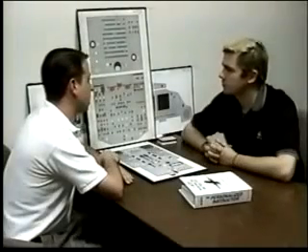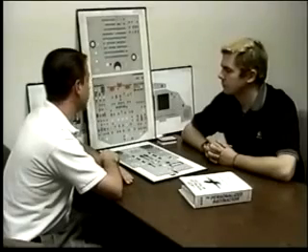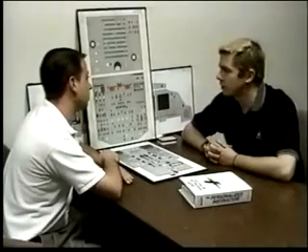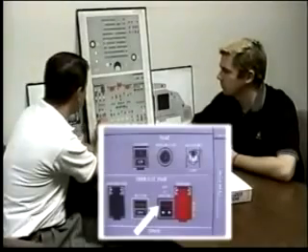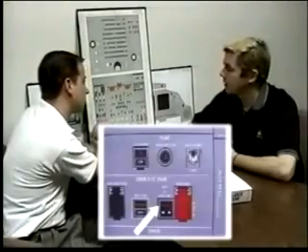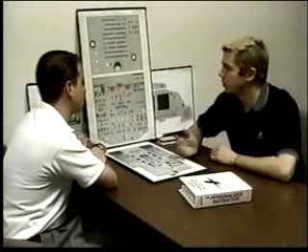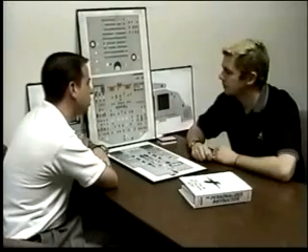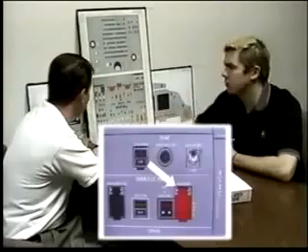You're on the approach, you go gear down, you go back to battery power. 2 batteries, 2 buses, 2 screens. Tower says, United 320, go around. Positive climb, gear up. Does the emergency generator come back online? Unfortunately, no. You look at the overhead panel, and you see a red fault light. What is that an indication of? That indicates that the emergency generator is not powering the system, and it should be. The nose gear is up, and you have no AC power. So how are you going to get the emergency generator back online? I'm going to lift the guard cover and select the switches under there.